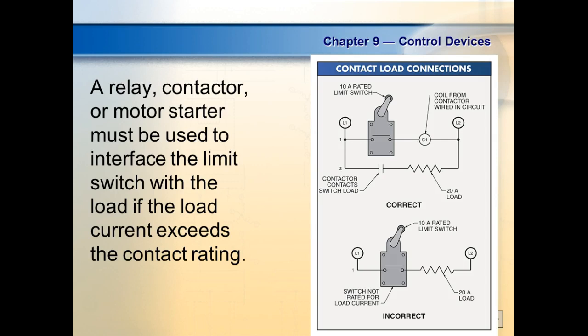So when we get into programmable logic controllers, what a PLC does is it allows us to replace every control relay. These are devices where their contacts stay inside the control circuit. Timers, we're going to get into timers later on. Their contacts stay inside a control circuit.